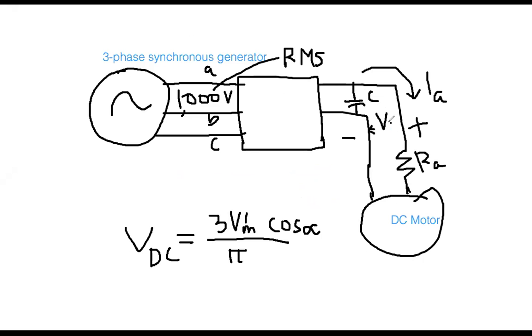And this is again your VT. So the structure is the same. And this is your 6 pulse bridge rectifier. This is called a 6 pulse bridge rectifier, this component that is producing DC where there is some ripple, that's why you are adding a capacitor.